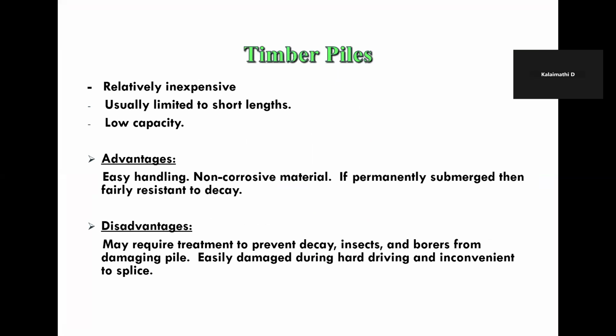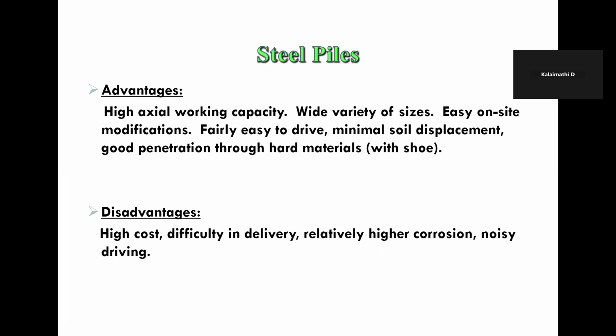Okay. Timber piles are really inexpensive, but they are usually limited to very short lengths and are of low capacity. They are easy to handle and not corrosive, but a very major and common problem with timber or wood related materials is attack by termites. Because of termite attack, the entire timber will disintegrate, and so our capacity will not be satisfied. So we are not using timber piles.